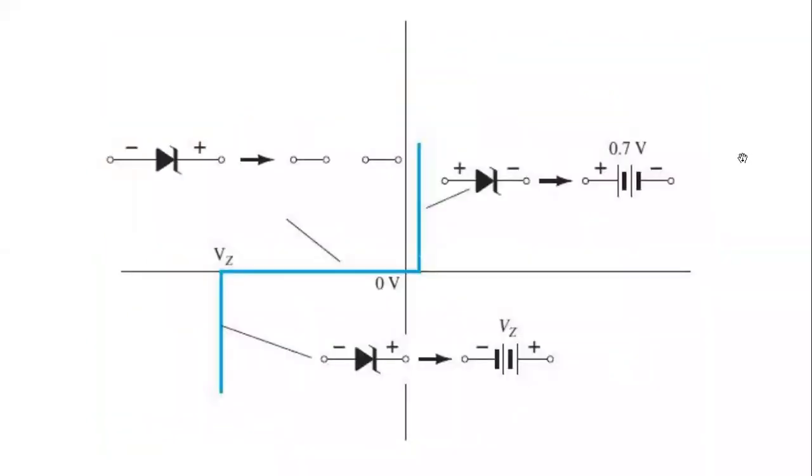So my students, the important factors now to come, the application of the Zener diode and how it works. Okay, so remember one thing: Zener diode is same as diode in the forward bias. You see that in this condition also, the Zener diode is same, 0.7 volt, like the silicon diode in the forward bias. But as I told you, the Zener region happens in the reverse bias condition. So when it is connected in reverse, at that time the main operation starts.